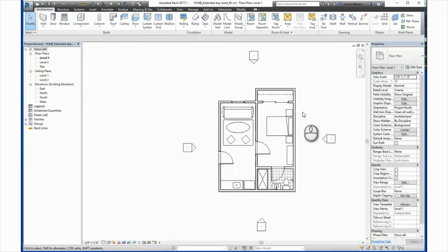Elements in Revit are family-based and grouped in categories. In Revit, the term family describes a powerful concept used to manage data and make editing easy. Each family element can have multiple types defined within it, each with a different size, shape, material set, or other parameter variables as designed by the family creator. Even when the various types within a family look completely different, they are still related and come from a single source, thus the term family.